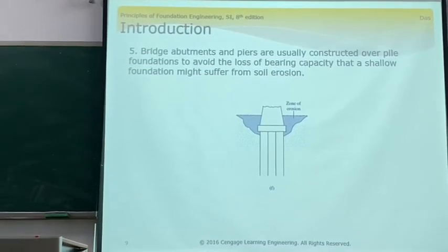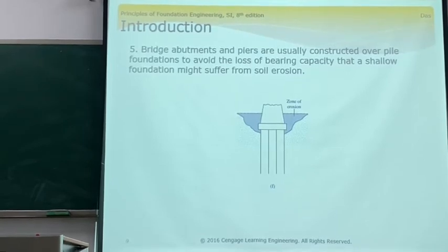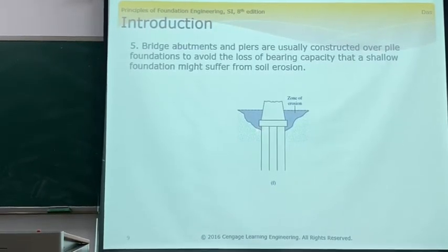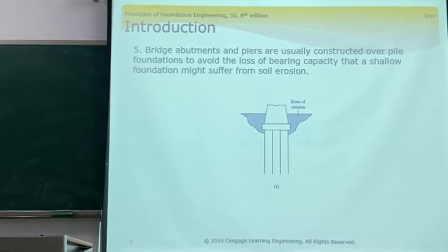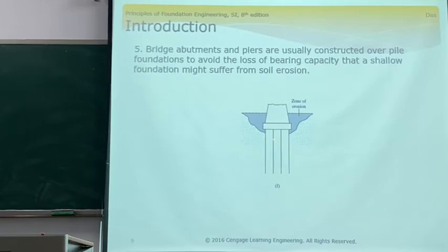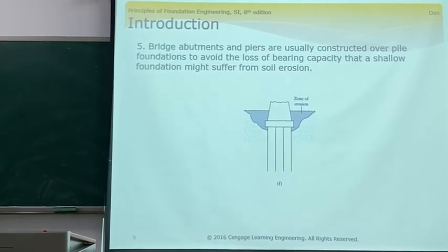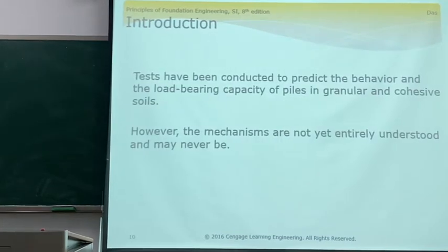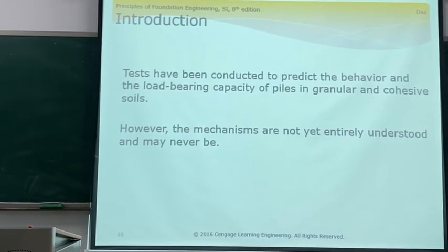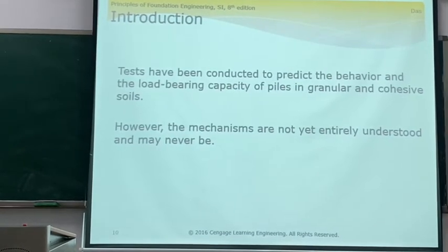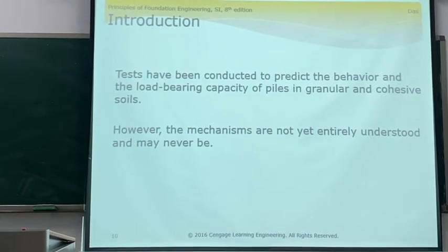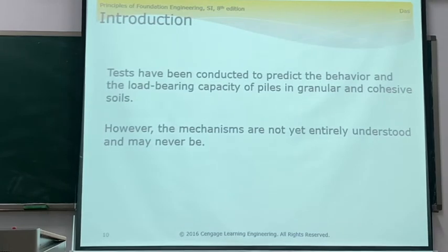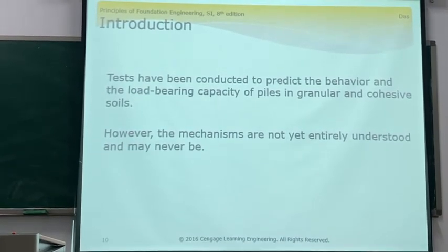Maybe after some years, part of the foundation will go out, so the stability of the foundation is not safe. So then we can use the pile foundation. Under this condition, we can choose the deep foundation, for example, the pile foundation, not the shallow foundation.